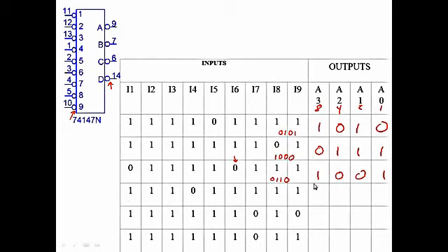Okay, let's see how you did. Let's see, this one's a 4. So a 4 is 0, 1, 0, 0. So it would be 1, 0, 1, 1. This one, since there's 2 of them, the highest one is the 9. It's going to be 1, 0, 0, 1, which inverted is 0, 1, 1, 0. And this one is a 7, so it's 0, 1, 1, 1, which inverted is 1, 0, 0, 0. So hopefully you got those. Pretty straightforward. Haven't gotten over the top complicated just yet, but we'll go on to the next one.